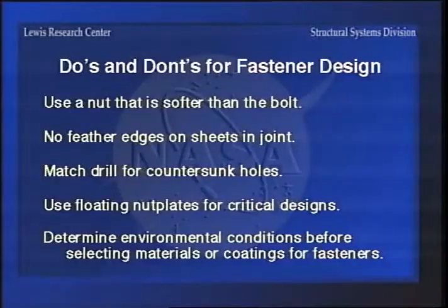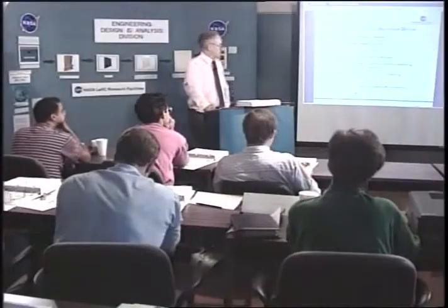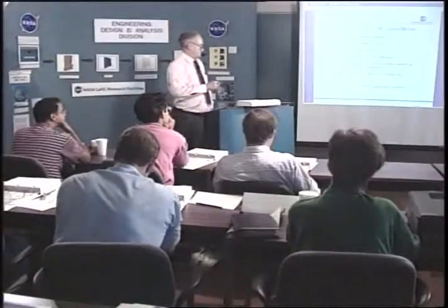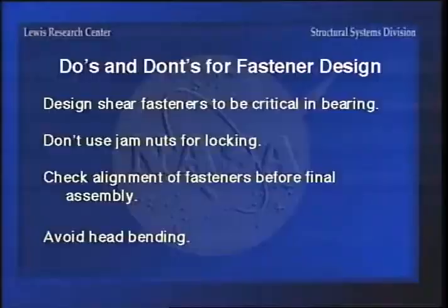And design shear fasteners to be critical in bearing. That means that the fastener is stronger in shear than the material, so therefore you can elongate the hole in the material to allow your fasteners to pick up the load without failing the fastener. Don't use jam nuts for locking. Check alignment of fasteners before final assembly.